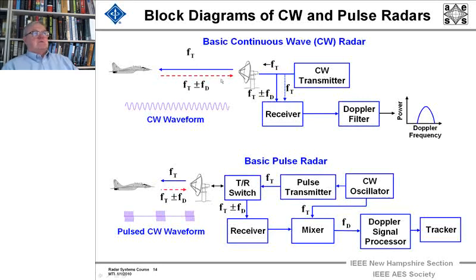You have a CW transmitter, and then a filter which would break away the transmitted signal, and you'd come into a receiver where you could separate these two and have just the Doppler coming in, and send it through a Doppler filter that was adjusted along with some other electronics to digitally tell you how fast the target is moving. And that's what the policeman reads.